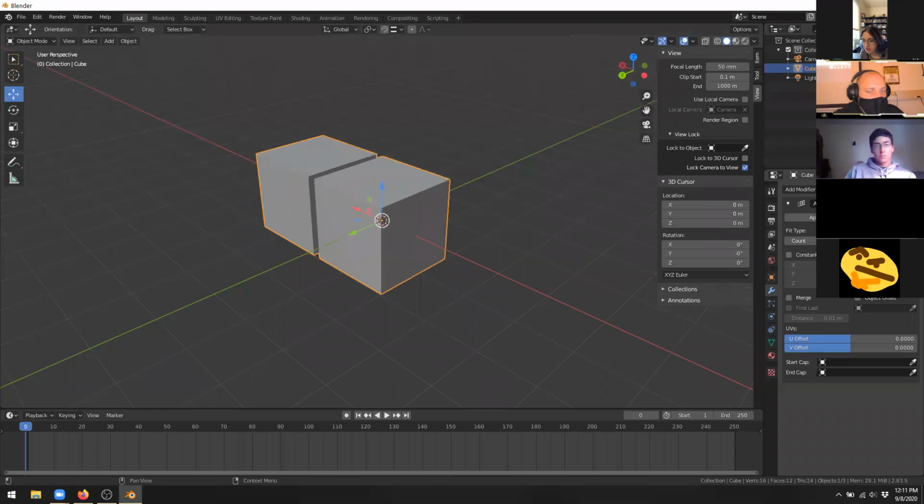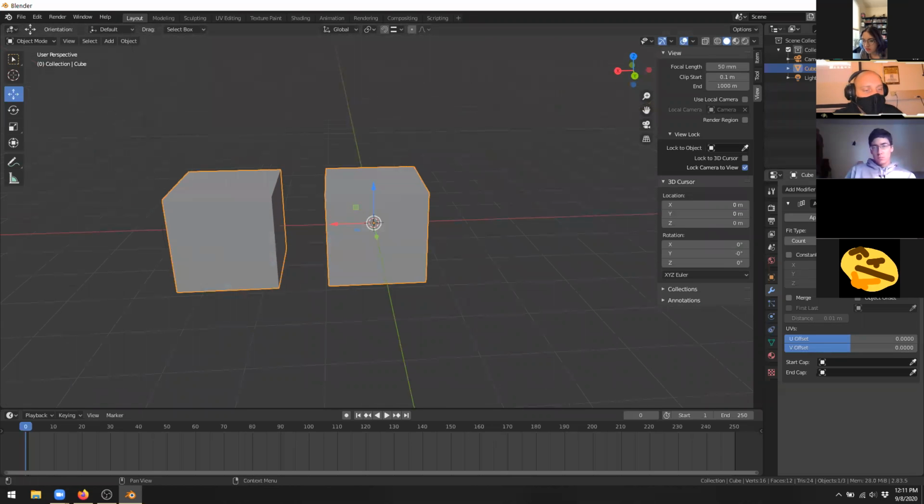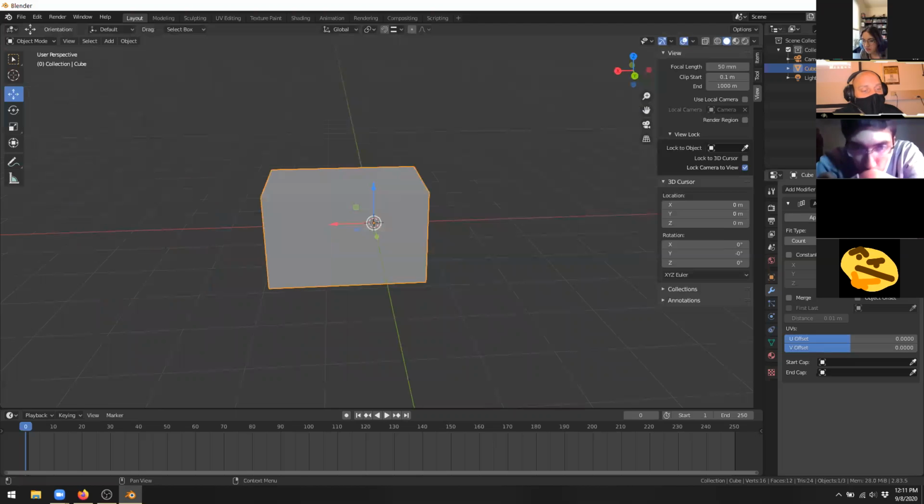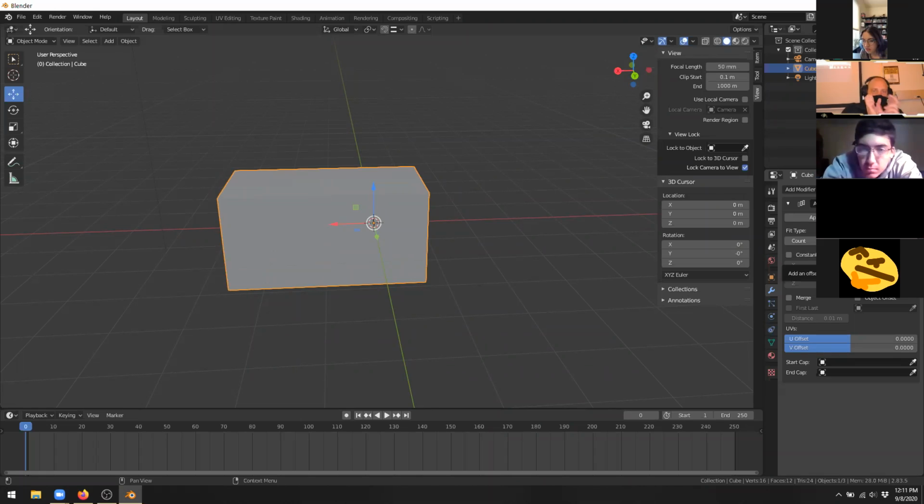The offset is basically the distance between them. There's two modes. You can use a relative offset, which is like a percentage, basically, how far away is one object from the other. So if the relative offset along, in this case, the x-axis is 1, it means it's 100% the distance away from the first one. So literally right next to it. If I set the relative offset to 2, there would be the width of one object in between those two.